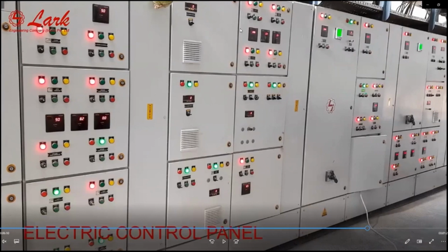even in the existing feed mills, we can install separate energy meters for the pelleting and the grinding section. As we are well aware, the ideal power consumption of a feed mill in poultry would be around 24 to 25 units per ton, excluding the boiler and the office and other loads. So if the power consumption is on a higher side, which section do we have to look at, either grinding or pelleting, or where we have to focus.